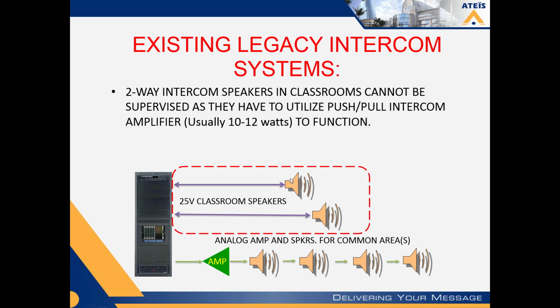It's usually 10 or 12 watts. Some are as low as 6 or 8, and I've seen some systems whose intercom amp is as high as 15 watts. But it's generally large enough to handle the biggest classroom or science lab that you would ever want to do intercommunications to. And typically, the largest I've ever seen in my 30-plus years of experience would be 4 speakers in a single room, and that would be a really big science lab. But most of them have 2 or 1 speaker in the room. And it's easy to talk to. You know who you're talking to, and you don't get a lot of background noise.